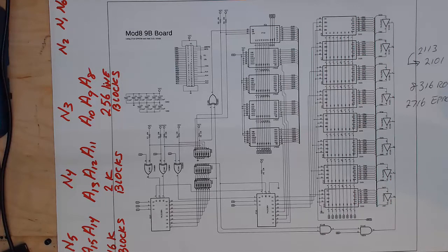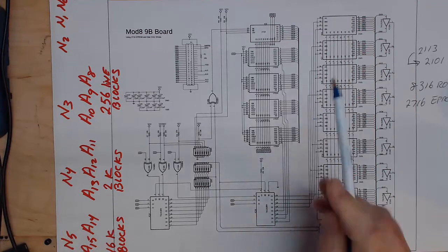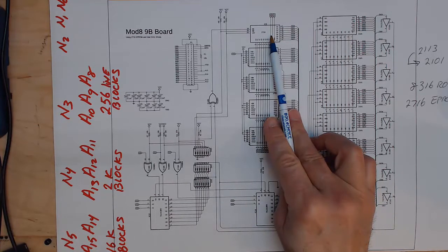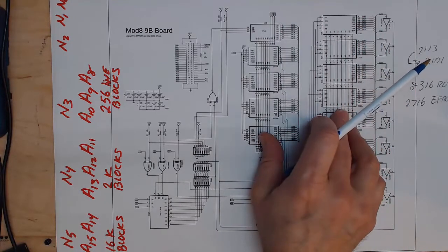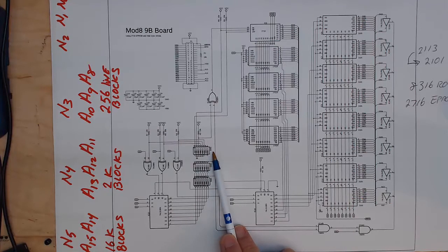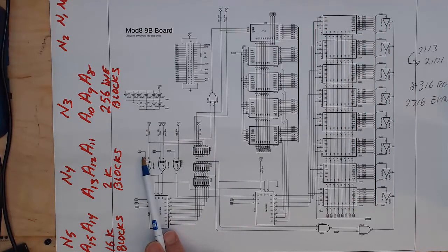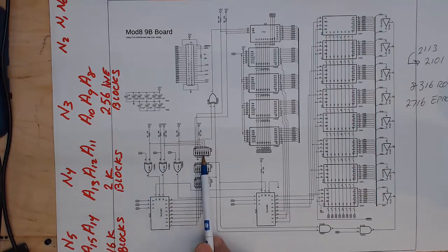First thing we're going to do is let's look at the N5, which is the overall board select. On this board there's 3 sets of dip switches. Switch 1 determines where the 2716 is going to be, or the original 8316. Switch 2 determines where the RAM and EPROMs are going to be, and switch 3 is an address configuration switch. So let's look at switch 3 first. We have address 15 and 14 come in, and those are exclusive ORed with 2 of the switches, switch 5 and switch 4 in bank 3.